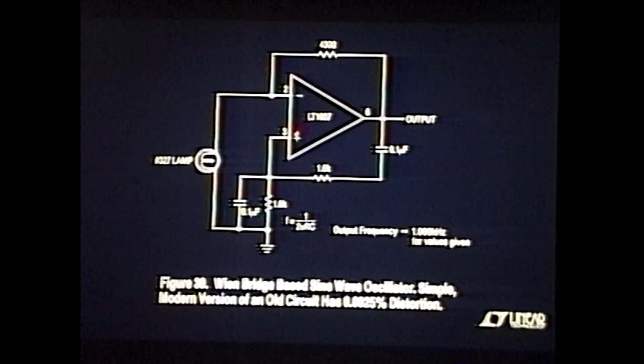The reason I got a lot of common mode here is because I'm driving the bridge single-ended with respect to ground. So if that point's moving and that's at 0, surely those points are going to move. What I want to do is lift up ground and drive it out of phase from the output. The most obvious way to do that is to invert the output at a gain of 1 and drive this point. You don't want a gain of half? Or gain of half, right, because of this. The problem is I'll never match the gain.